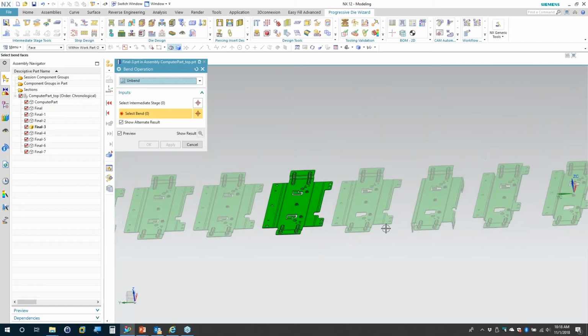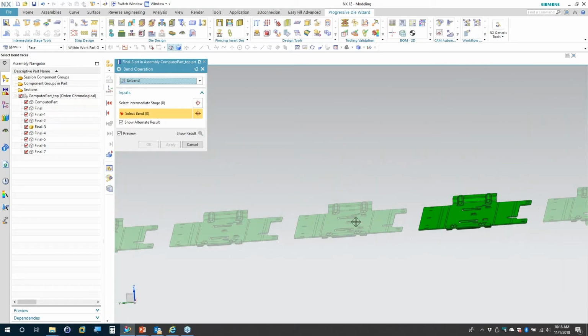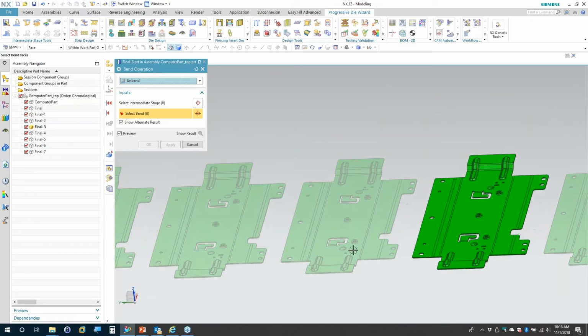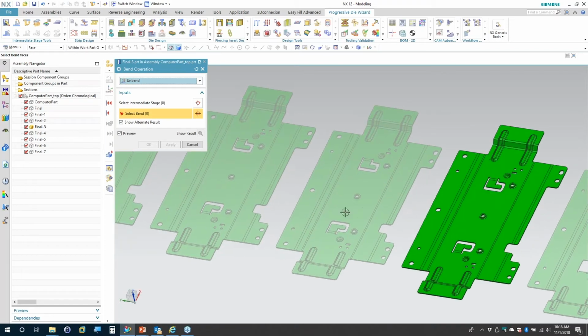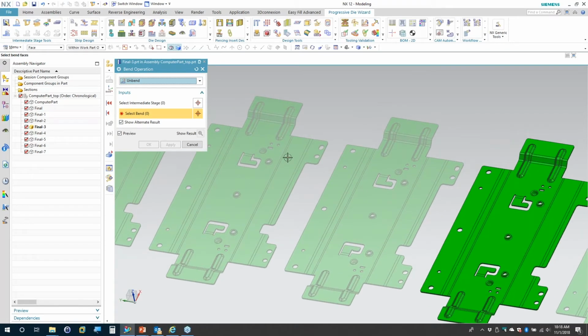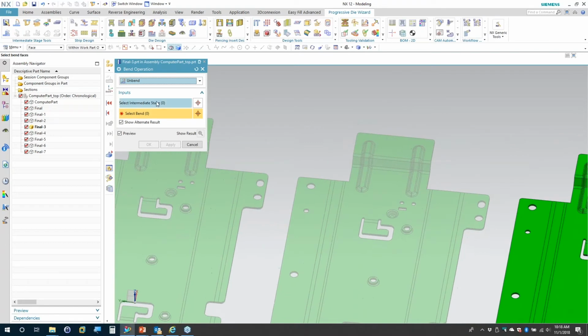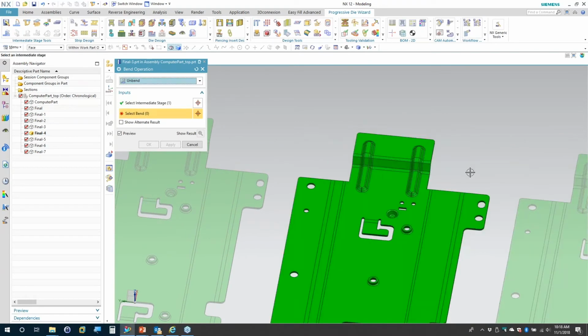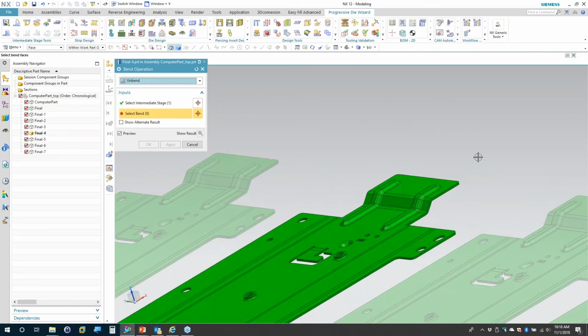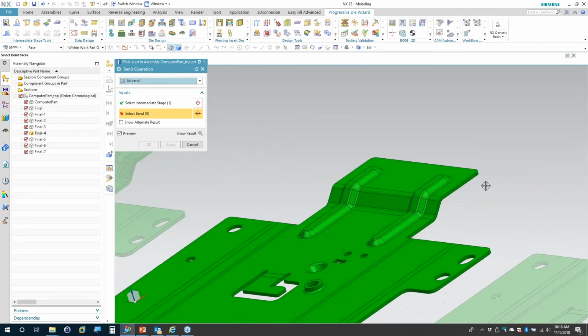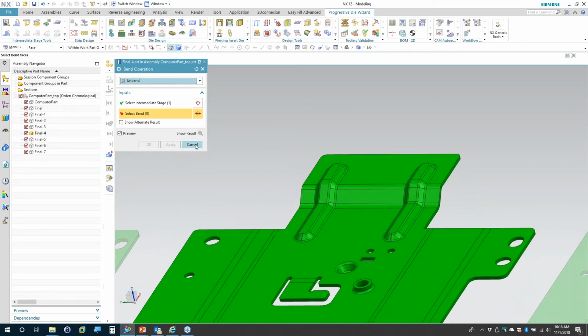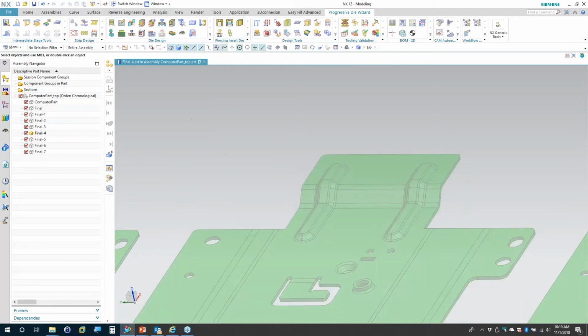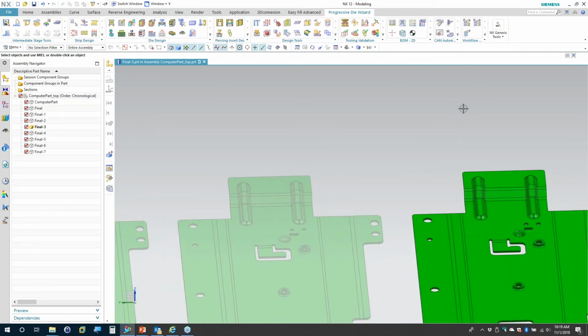All right, so now we've already worked our way back to a flattened shape where these flanges first get formed and the internal flanges are done. So let's take a look at what we have next in this stage: the flanges on the ends that have these beads that are formed. So there's not really technically any unbending that's involved with the forming of those beads. So we're going to use some standard modeling tools to represent this in a flattened shape.